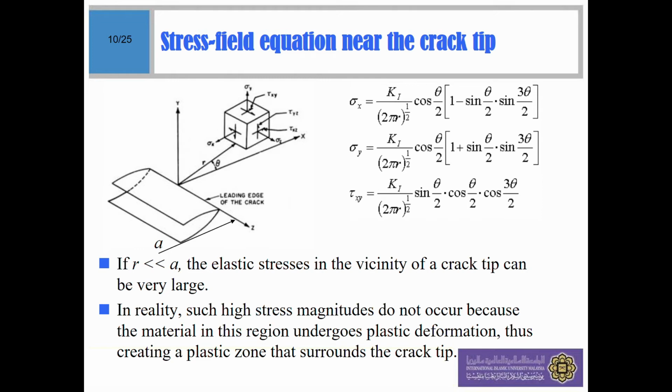It is the same with the crack tip. Once the crack tip has reached the critical value and is propagating or enlarged, it is no longer in the original position. Once you release the load, of course the crack tip won't go back to the initial position. That's why we say the material in this region will undergo plastic deformation, which also creates a plastic zone surrounding the crack tip.